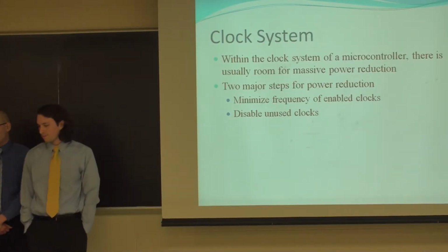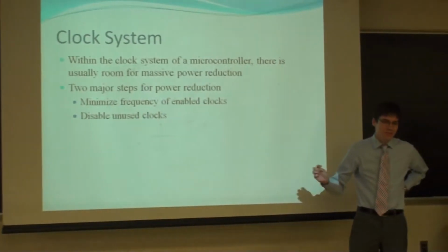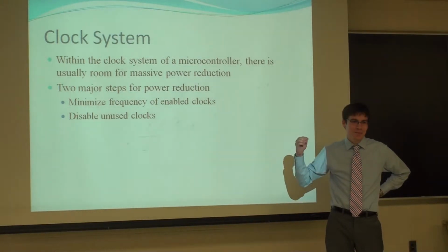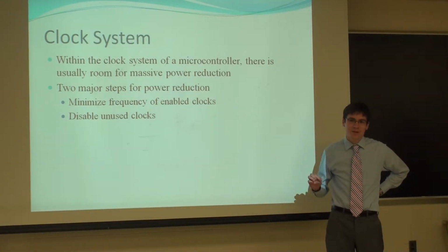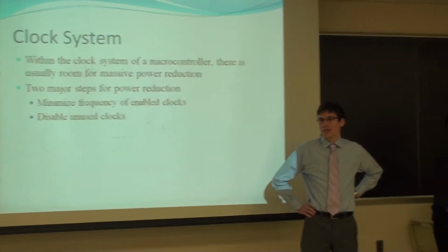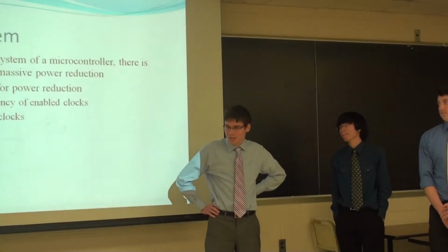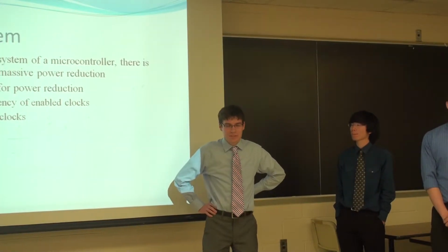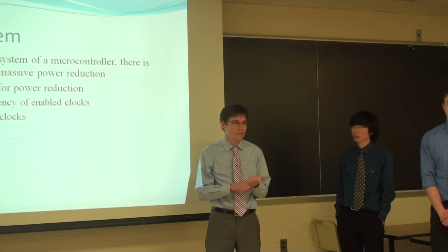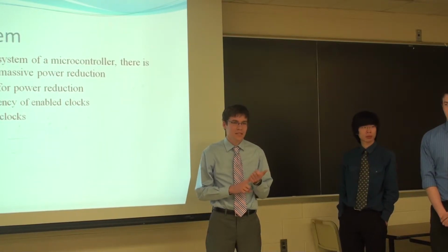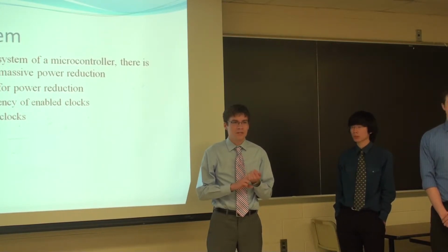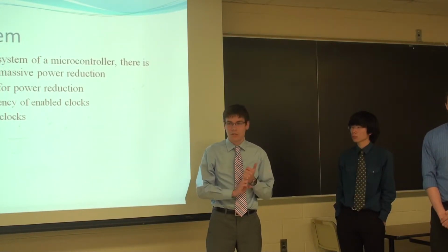Okay, so Tim mentioned a really interesting design concept, which is to first try to maximize performance and then work backwards from there to try to reduce power while maintaining as much performance as you can. And a great first place to start when you reach that point in a low power project is the clock system. Today I'm going to be talking specifically about two microcontrollers, the MSP430, which is in TI's low power Launchpad development boards, and also the ATmega 328P, which is the low power variant of the ATmega. It's in a lot of the low power Arduinos.